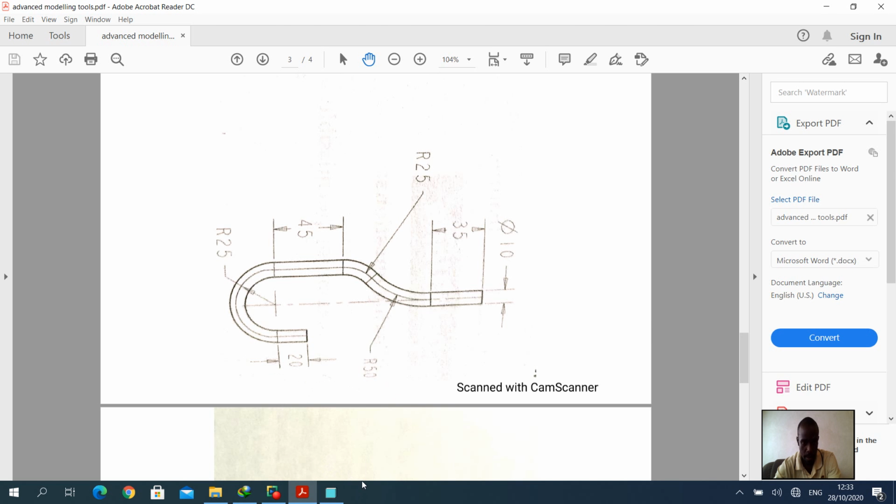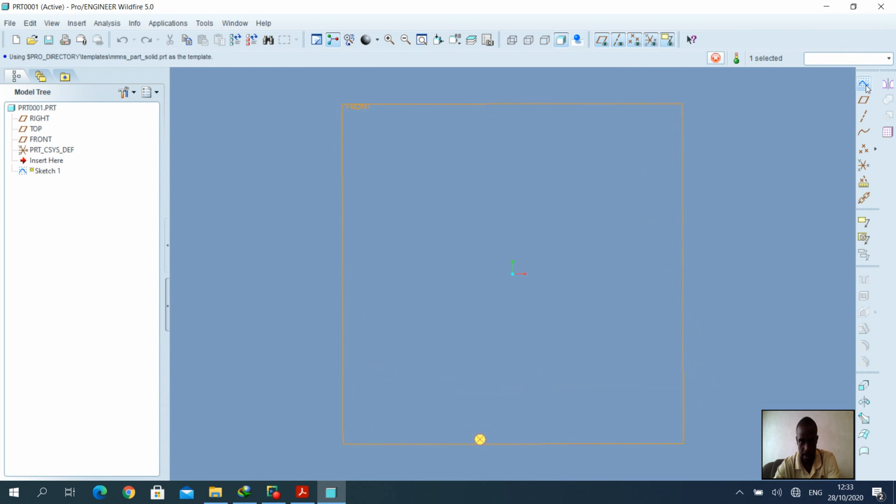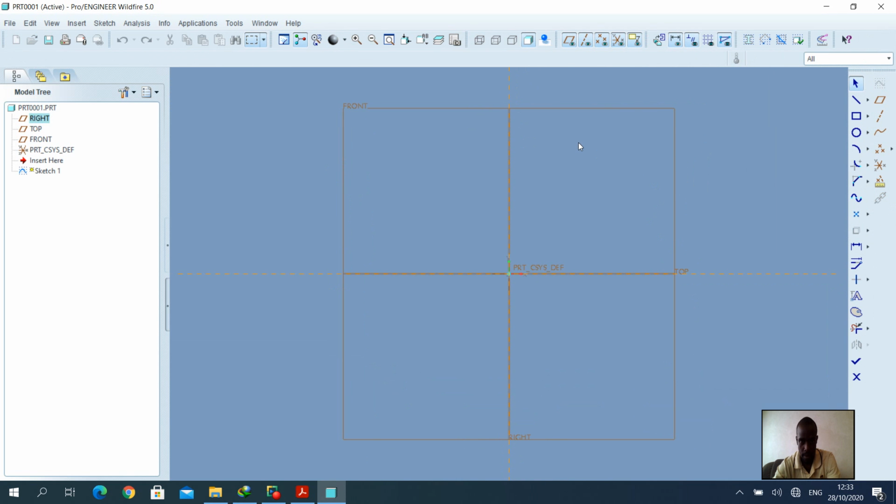So how do we make this thing? What I can actually do, it's not always the case whereby you can start, select the two and then start to sketch. We can actually sketch the trajectory first, and then we can select it once we assign our attributes in our sweep operation. So I'm going to be selecting sketch, and then let me make this component.